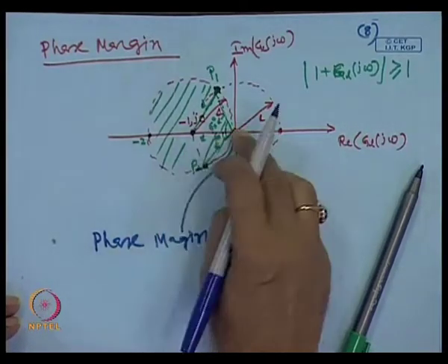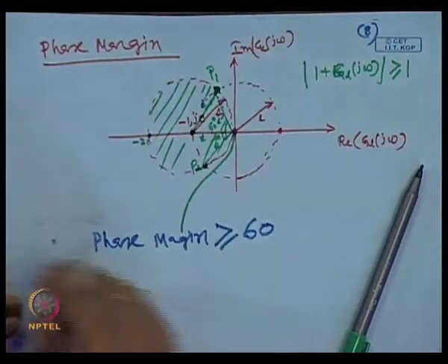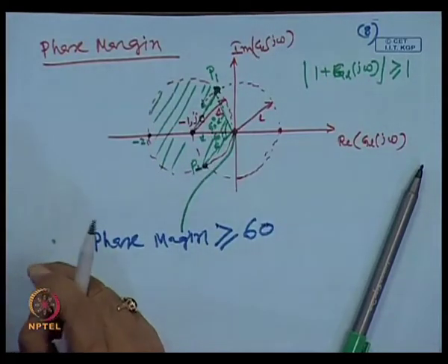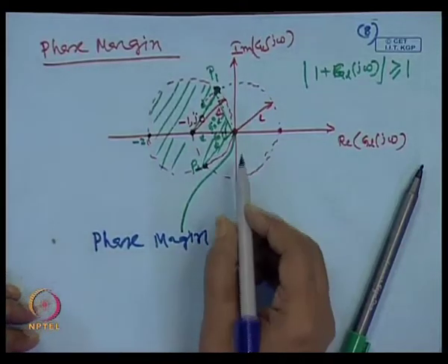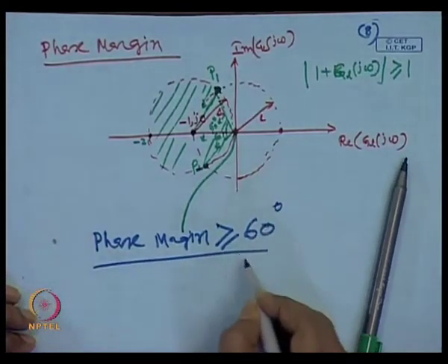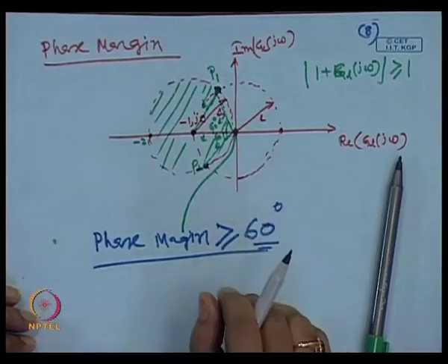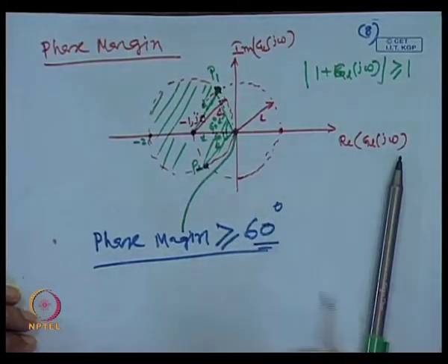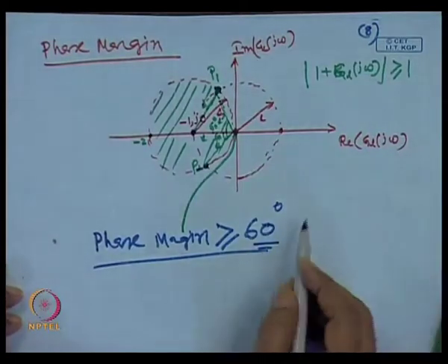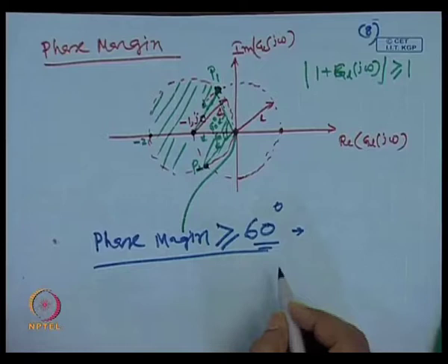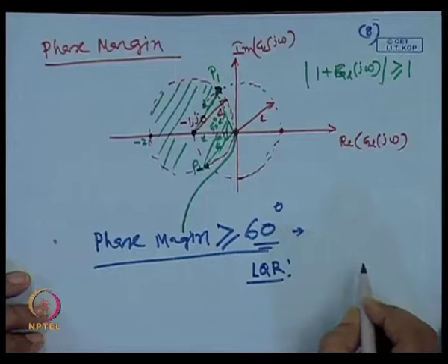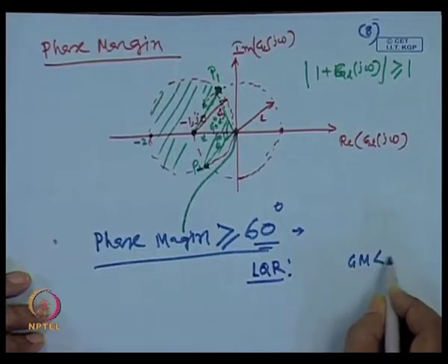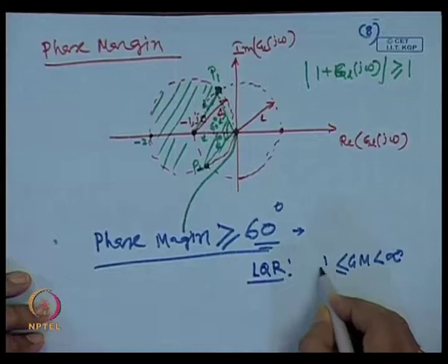If it could enter here, it would violate our condition which we derived from the algebraic equation, and the algebraic equation comes from the design of the LQR controller. So, our phase margin will be greater than or equal to 60 degree, at least 60. This is the phase margin. In short, if you design the LQR controller, it ensures that our gain margin is infinity and half.